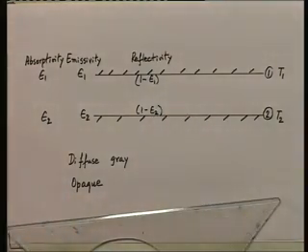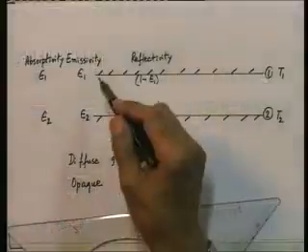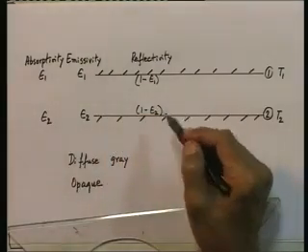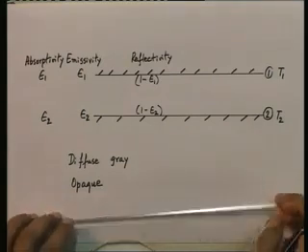Therefore, absorptivity plus reflectivity must be equal to 1. So, this is the characterization of the surface. A two surface enclosure made up of two infinite parallel plates, diffuse gray surfaces, opaque surfaces maintained at temperatures T1 and T2. Emissivity and absorptivities are epsilon 1 and epsilon 2. Reflectivities are therefore 1 minus epsilon 1 and 1 minus epsilon 2.